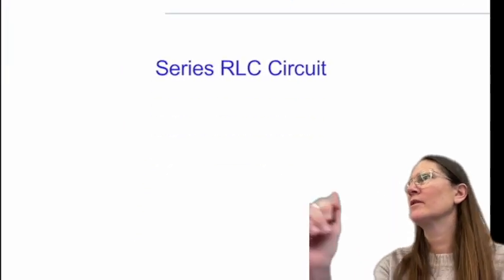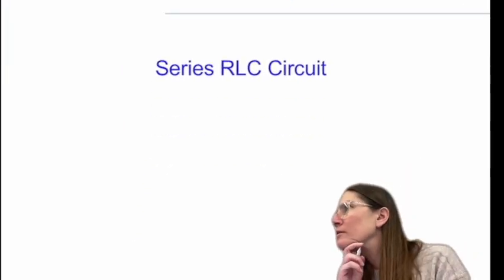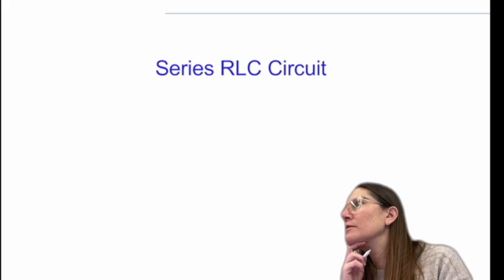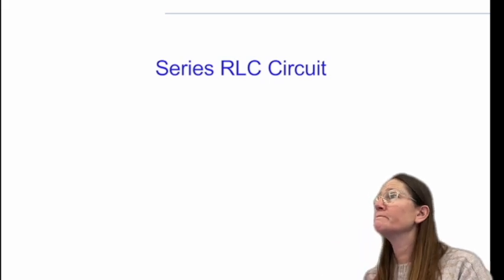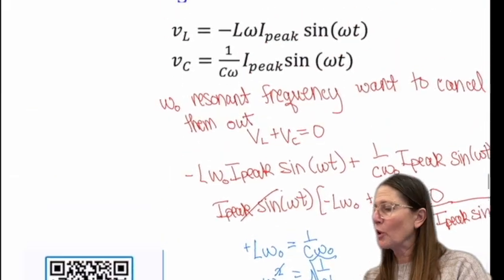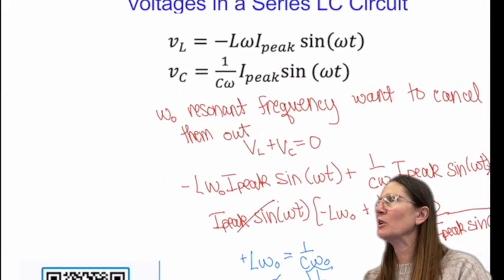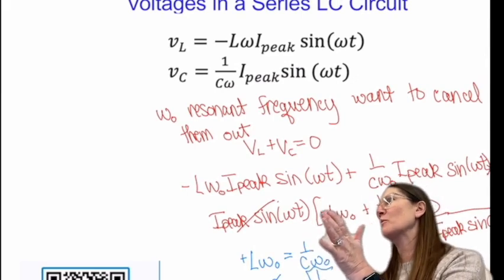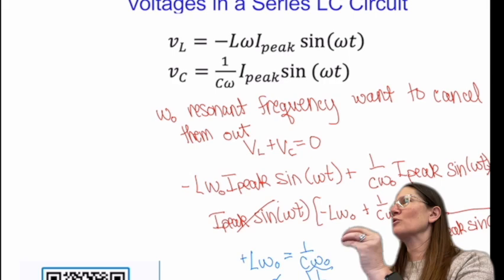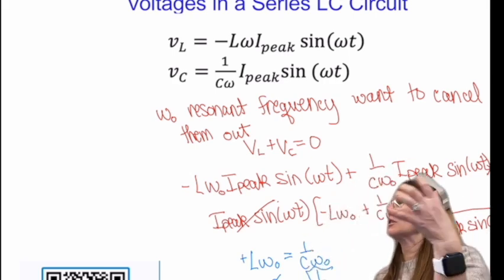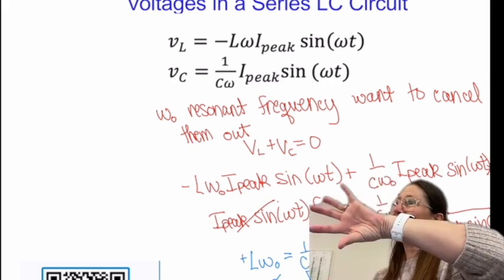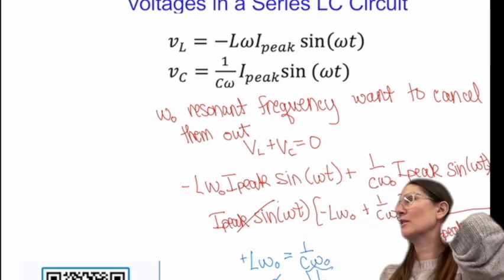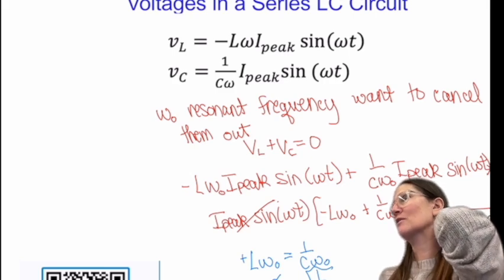Would that work if you were to find the equivalent inductance and capacitance, if you had multiple inductors and capacitors? Yep. So remember, the root is when you have 0, when your quantity becomes 0. So that's also the same kind of idea: we're taking these components and canceling them out to be 0. And so that root of the system is the same thing as a resonant frequency.